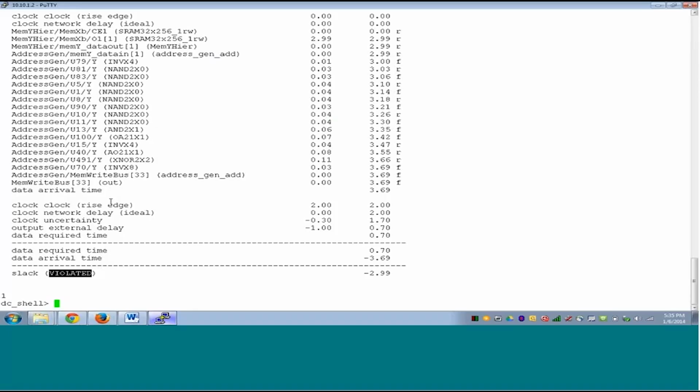Also, please go and analyze the design yourself. See what all design guidelines are not followed. For example, if the inputs are registered, if the outputs are registered, and so on. Analyze that problem, correct it, and using the same library, we saw that the timing needs at about 300 megahertz. Maybe you should try and make this design work at 350 or 400 megahertz by doing some design changes if you can. So that's a significant assignment for you to follow.